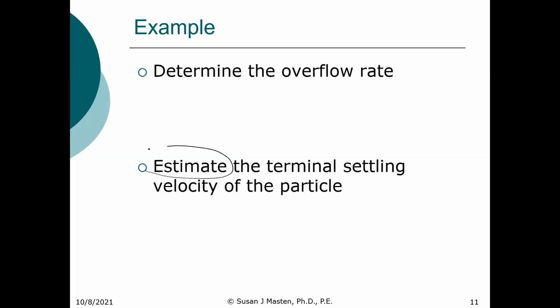Why do I say estimate? Is there any piece of information that at this point we don't know? We don't know whether we have laminar flow. We haven't determined the Reynolds number, and Stokes' law depends on the Reynolds number.